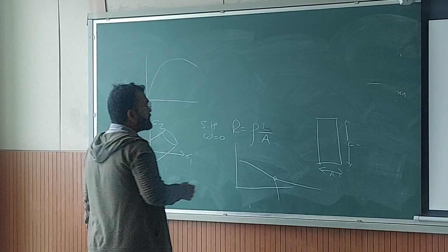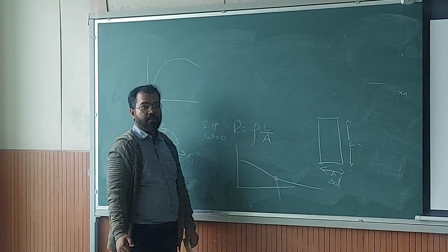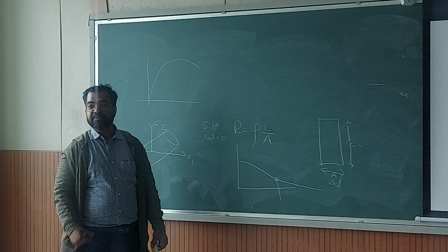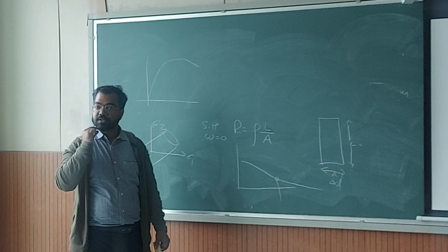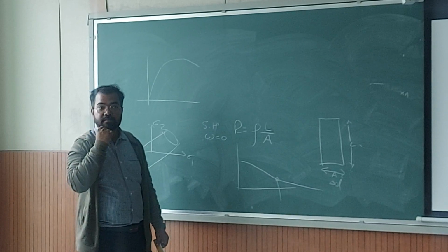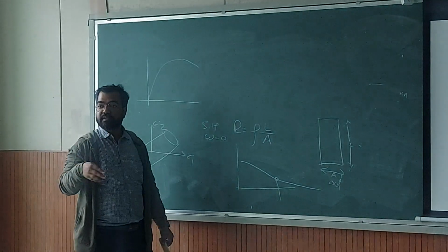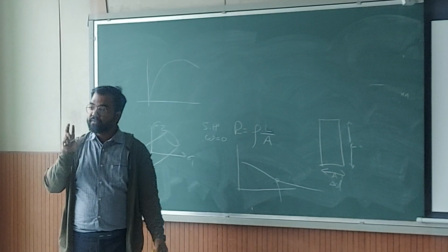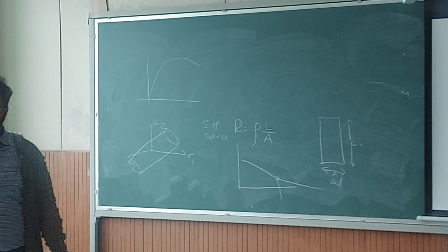So change in A can be written as change in diameter, right? And change in diameter per unit change in length is represented by Poisson's ratio. Poisson's ratio will change when plasticity begins, right? Whatever is the value, 0.3, 0.45, it will change to 0.5 when plastic deformation happens.